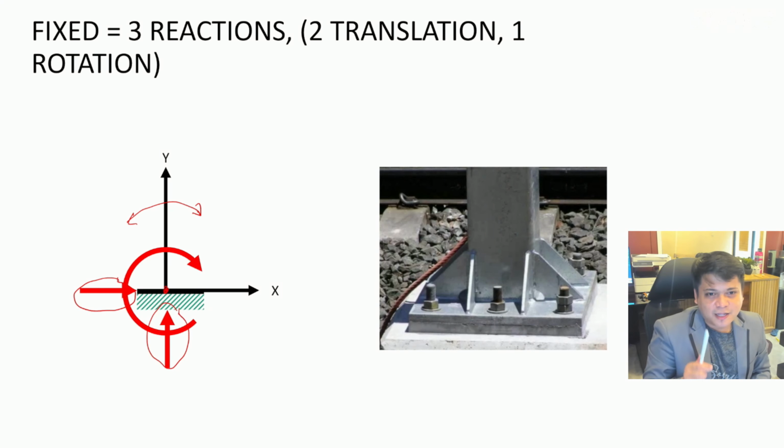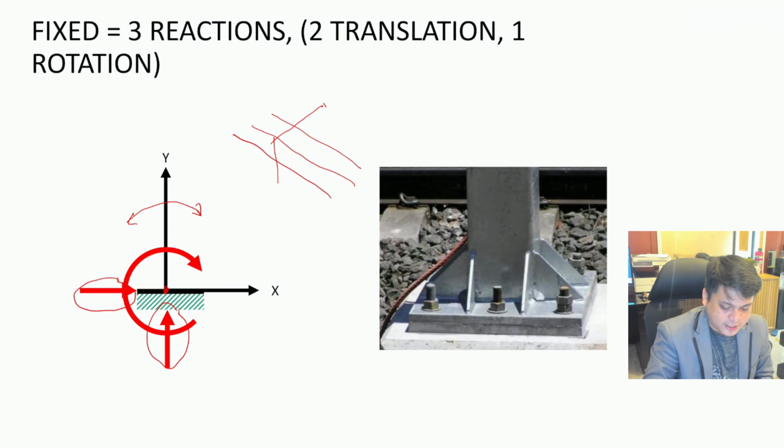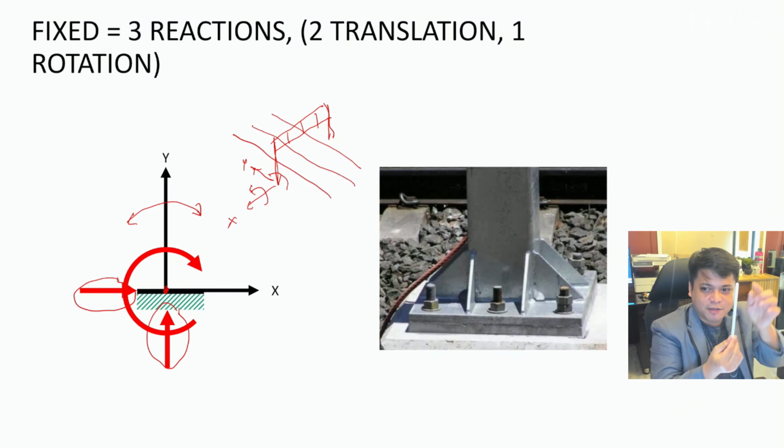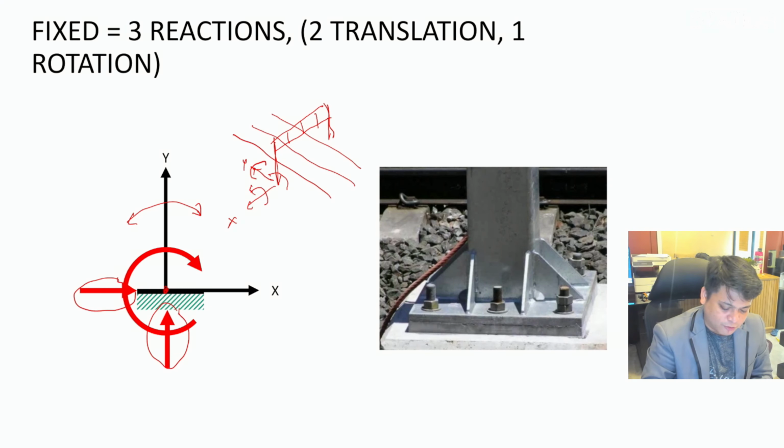For one or up to two legs, for example, what is a good example? Okay, if we go to EDSA, for example, the highway. The highway has two lanes. Then there is a signage, the MMDA signage, for example saying to SM North or to Bulacan. So you have two columns. Its support has two directions again. You have a direction here, and then a direction there. So for this rotation, let's say X and then Y, the moment in X is required to have a fixed connection. Otherwise it will topple, because it does not prevent rotation. But for this other moment, you can already pin it.